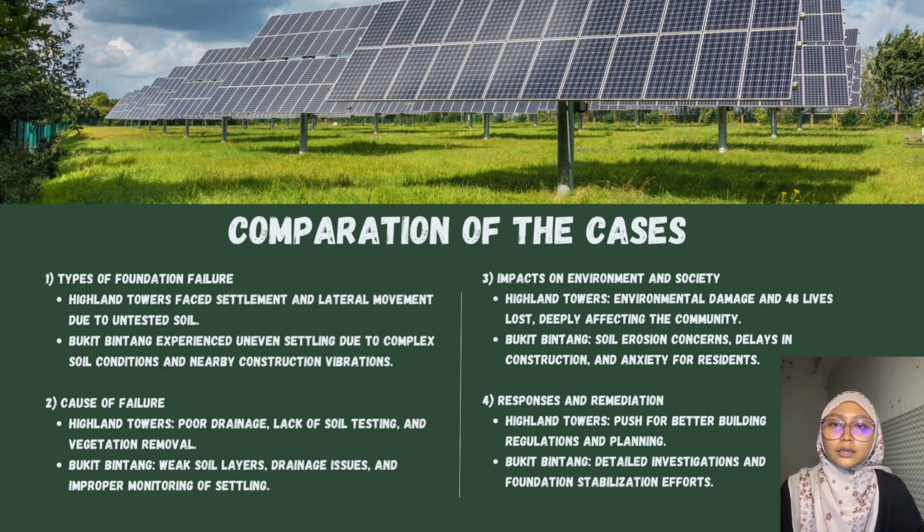In Bukit Bintang, the problem was different but related. Here, the building settled unevenly. This was caused by the combination of complex soil conditions and vibration from nearby construction. This example shows how ignoring soil properties can lead to serious foundation problems that compromise the safety of a structure.